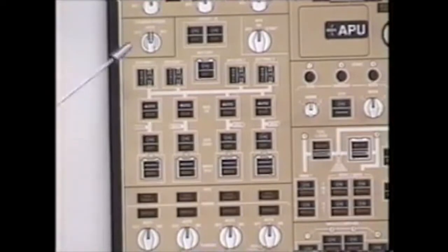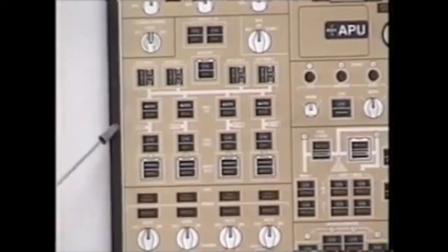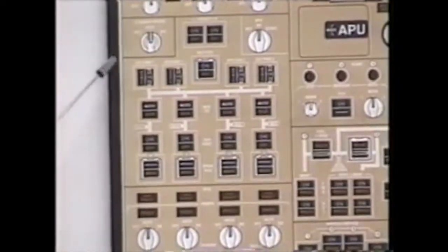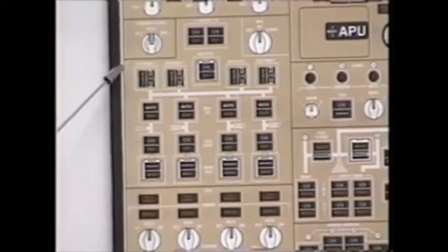Continuing with the electrical panel, in addition to your AC buses we see depicted here, there are 2 additional buses I'd like to think of here on your electrical panel. One of them is physically placed here in relation to your system, the other one physically placed here. The bus up here to the left of external power 1 would be the ground handling bus.